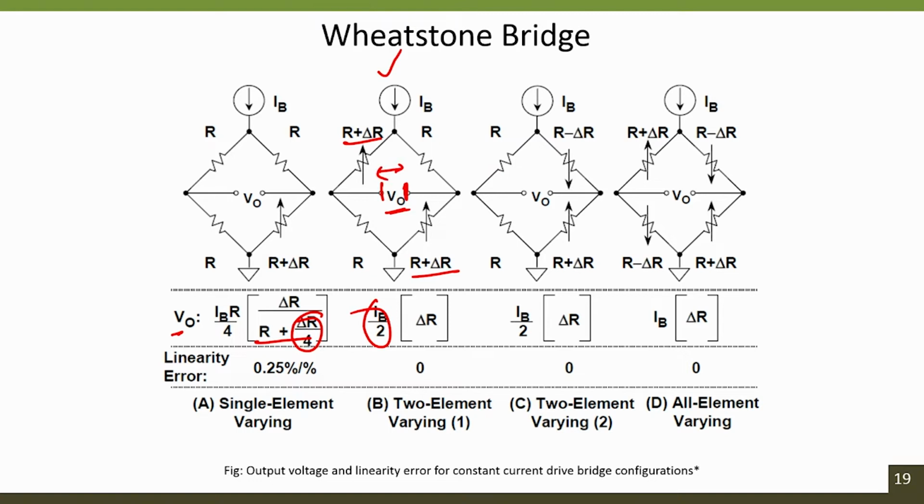So in such cases, we cannot use either an inverting amplifier configuration or a non-inverting amplifier configuration, because these configurations can only amplify or attenuate a single input voltage with reference to the ground, whereas in this case the input is differential.